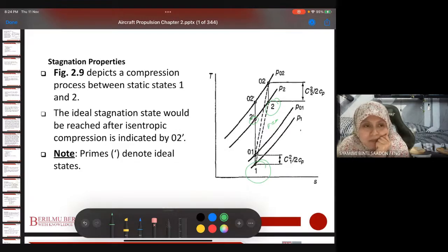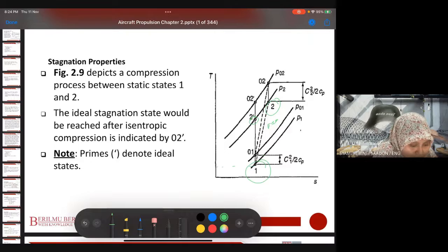Okay, now with the knowledge of the stagnation state, there is a slightly difference of temperature location. For example, at T1, with the static temperature, we have T1 lower than T total 1, T01. For example, if T1 here is 20 degree, but the actual total temperature at location 1, inlet of the compressor, is actually maybe higher, 30 degree.